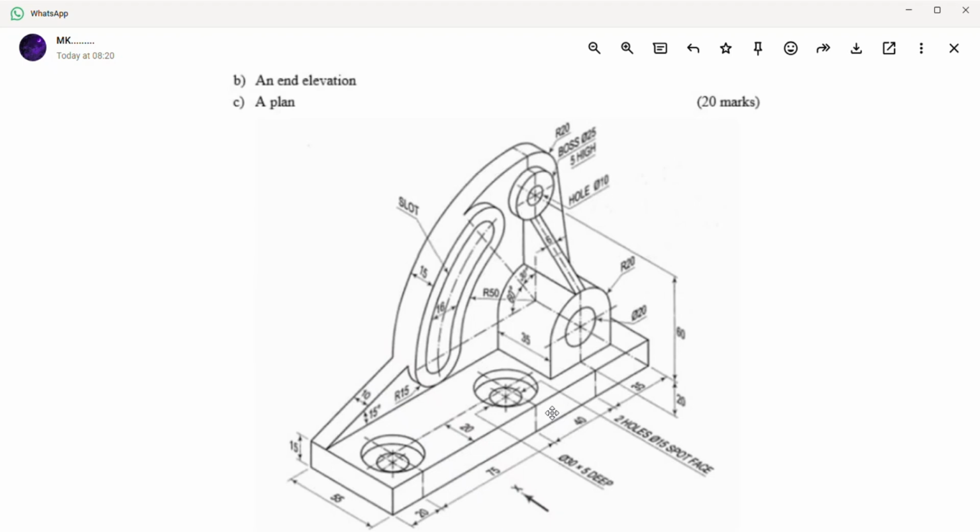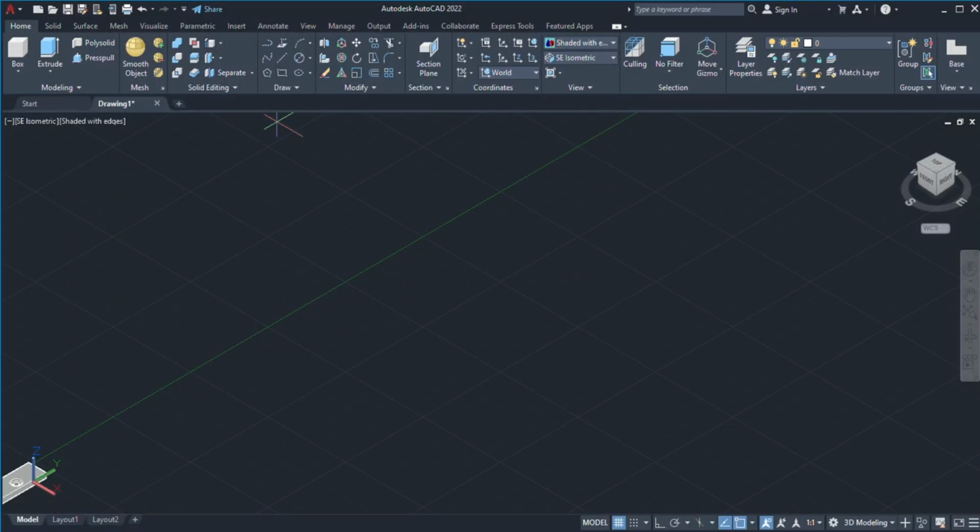So guys, in this tutorial we are going to be completing this question. We had done it previously in the first lesson and we only did the base. So we are going to be doing the right plane and the front plane. We are going to start with this base that was 55 by 170. So you type 55, then you tab, 170, enter, zoom in.